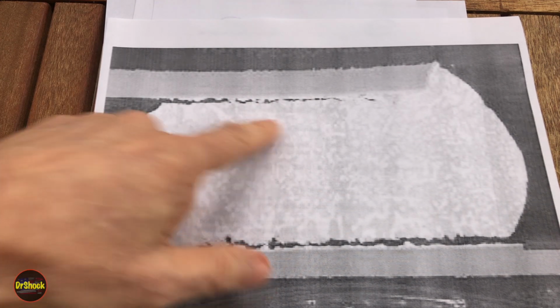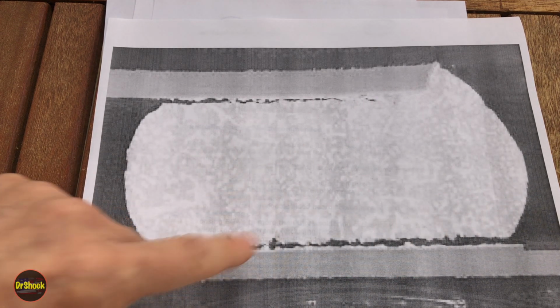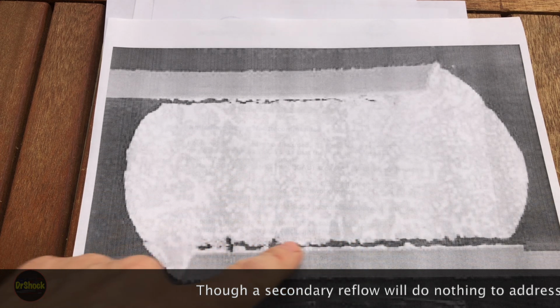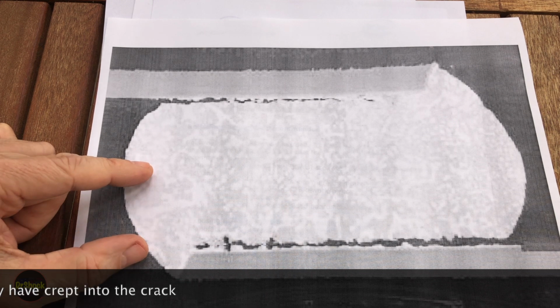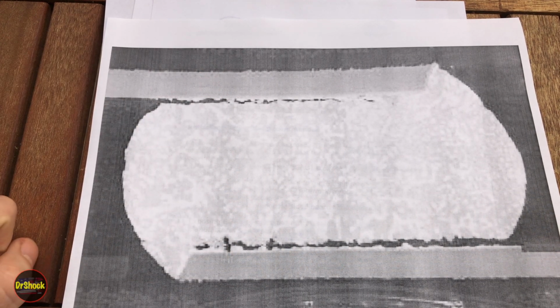And so when we do a secondary reflow, what we're trying to do is get all this to fill back in, because in this case you still have contact here and here, but you can have a situation where this is completely separated and there is no contact. It's very similar to, on a much larger wiring system, a cold solder joint or something of that nature. So that's what we're aiming to do with this secondary reflow.